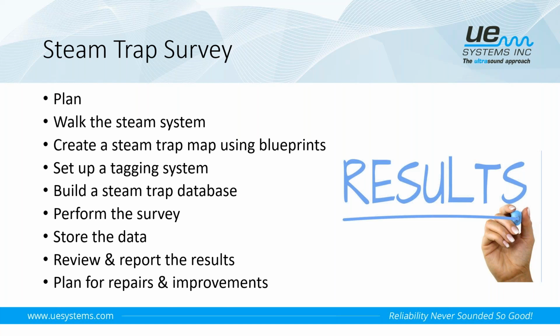Everybody would be doing it, but it's work that has to be done. So maybe you can start with your blueprints, and then you've got to get out and walk the system and know the areas where the steam is in use. Know the areas where, like I said, maybe it's no longer in use and hasn't been for some time.